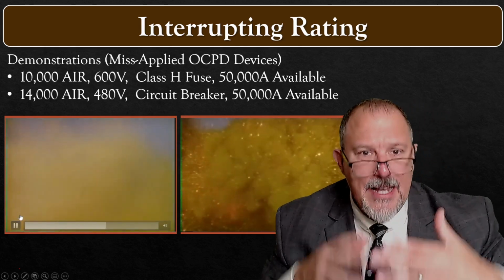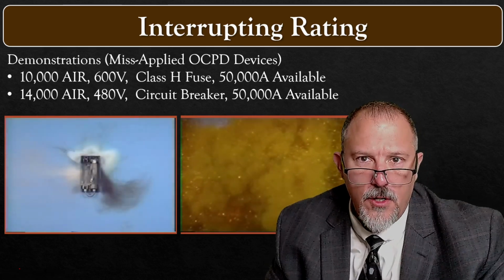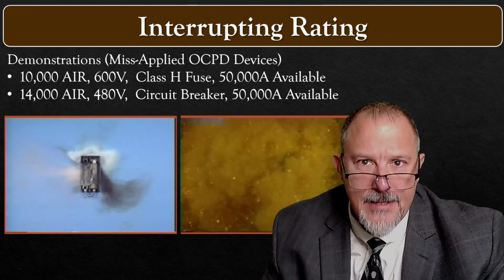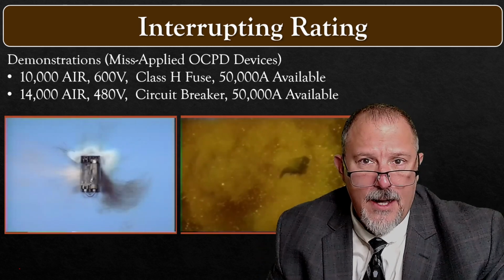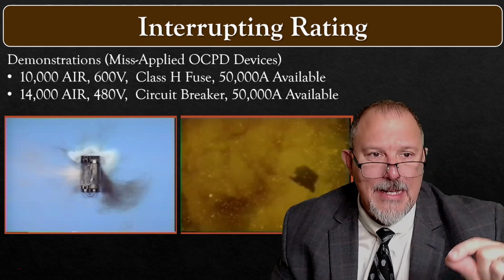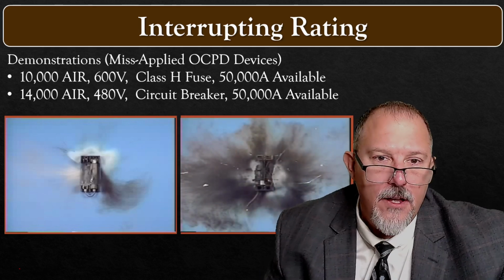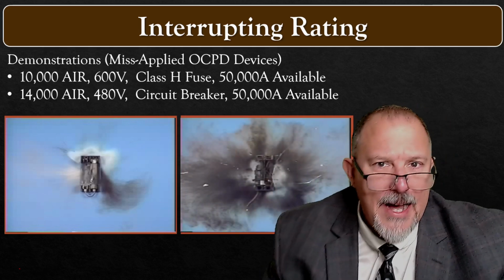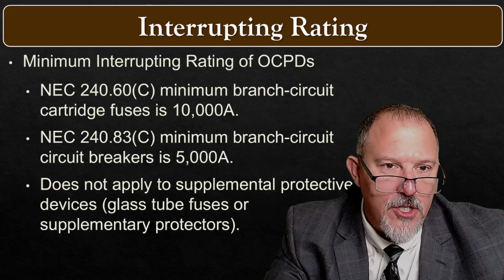If you exceed the interrupting rating of a circuit breaker or a fuse, this is a serious misapplication. I don't care if it's a fuse or a circuit breaker. Interrupting ratings are very important, and it's at rated voltage: the highest current at rated voltage. So voltage and the amount of current are going to play a role.